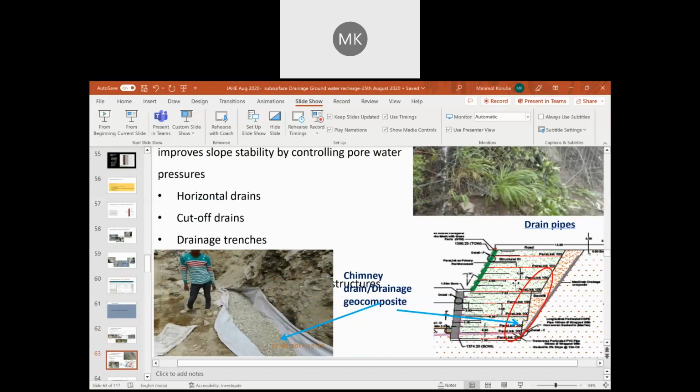Whereas a fin drain is a longitudinal drain where you are placing a geocomposite as such. Okay, so I'm not going into the very details because we have talked about it continuously. Figure 4.5.2.7, the fin drains, which is given in IRC 34, the same image I have taken here, just copy and pasted. Okay, so two types of fin drains, a drainage geocomposite. The first one, the left one, is without the pipes, and the right one is with a pipe.